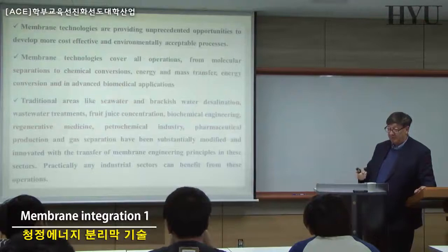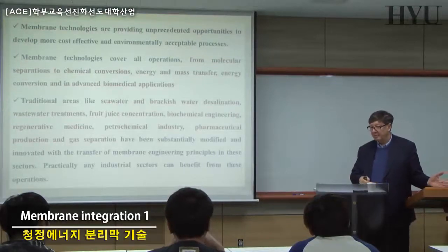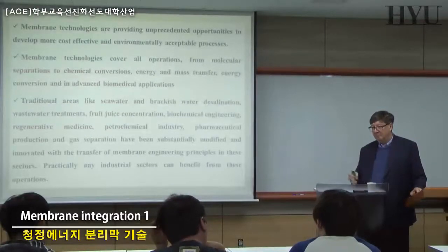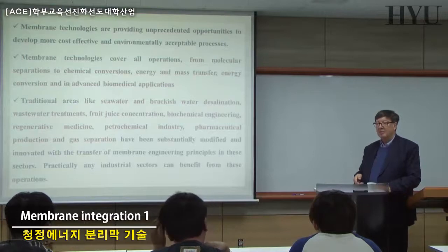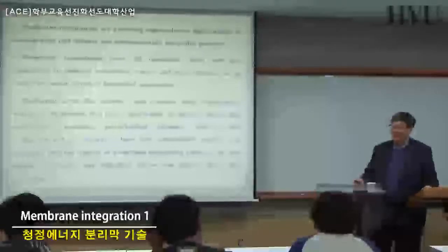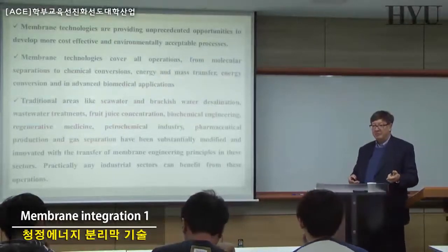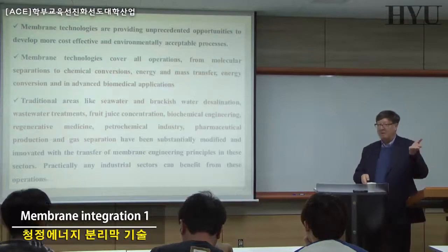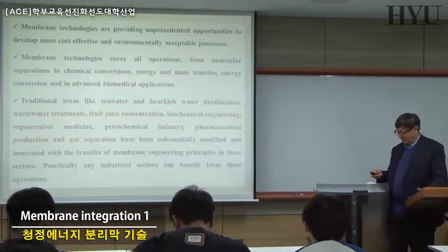All the good beer that you are drinking today, the water for the preparation of beer goes through purification with membranes. For all the wine that you are drinking, in the production line there are 2 or 3 different membrane operations. The standard one is before bottling. Before bottling, you have this last purification from microorganisms, done by standard microfiltration. But today, you also have a lot of other processes. Reverse osmosis is used to increase the sugar content, for example, before fermentation. If it's raining during the harvesting, as this year, you have to increase the sugar content a little bit, so they use RO. But it's not visible, it's not talked about much, but a lot of membranes are there.